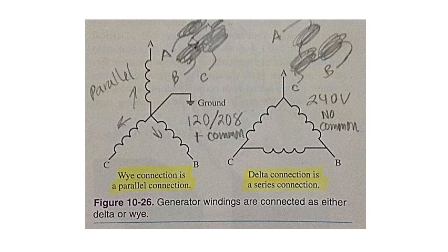Delta is used mainly for heavy industrial work or loads, while the Y connection is used to support both power and lighting circuits. The delta and Y connections are covered in detail in chapter 12. While some equipment will operate on either voltage, it is best to connect a piece of machinery to the voltage level specified in its operator's manual.